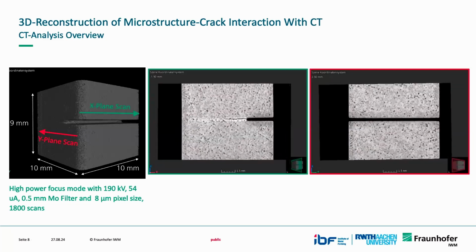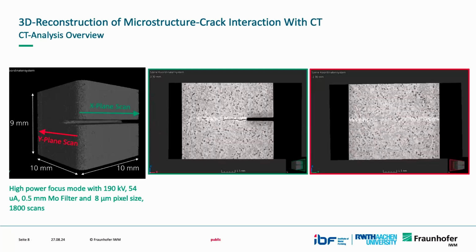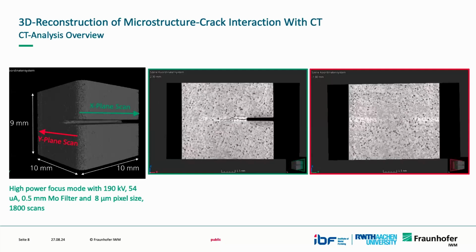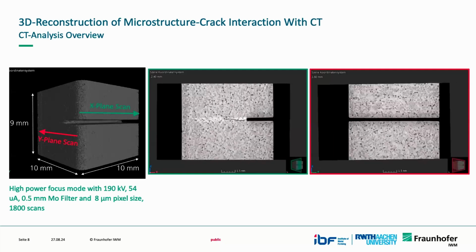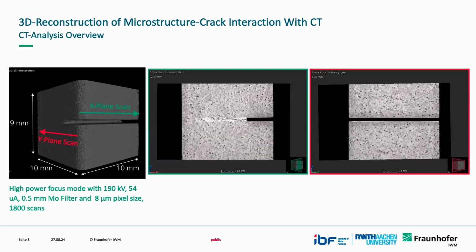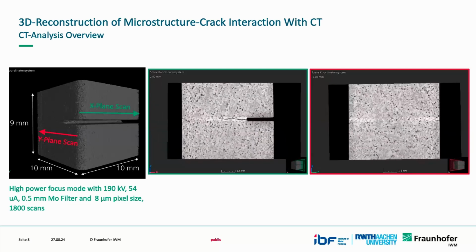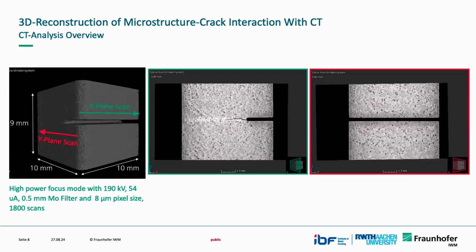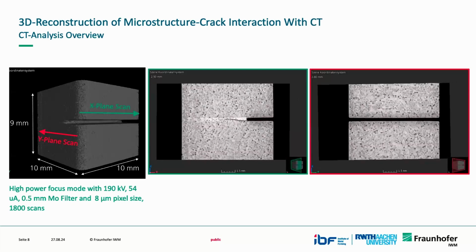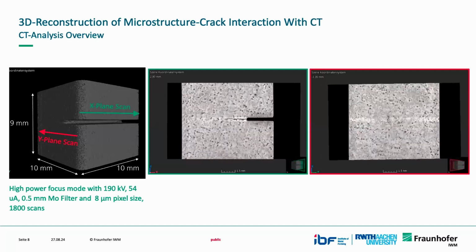This is the second part. So we're going to be dealing with computer tomography. And what we did here was, this is preliminary results. So what we tried to do is we scanned a pre-cracked Charpy specimen with a fatigue pre-crack. You can see here these two different scans and directions. So we have the erosion notch here, and you can see here very, very nicely the fatigue pre-crack.